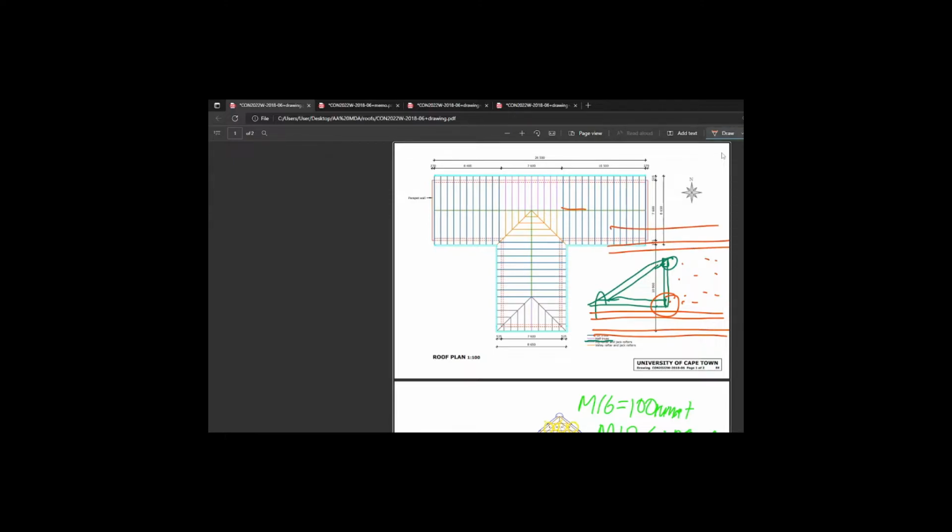Bunch of full trusses and full tie beams, full length tie beams, put it that way. This is a half length tie beam. So void over here in your tie beams, there's no void in terms of your jack rafters. These are all jack rafters. So the top of the roof still has to be supported, obviously, for our battens to fix onto, but there's a gap underneath here where there's no tie beams that don't extend.